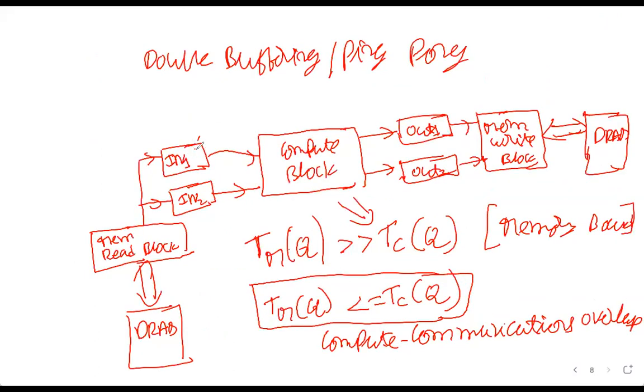The design of these buffers in1 and in2 is very important. The way it is drawn, it looks like a queue, but you want to have in1 divided into multiple partitions, and each partition allocated to a separate VRAM block. That way the compute block will get maximum bandwidth from this buffer. If these VRAM blocks have 2000 read ports, then the compute block will be able to do 2000 parallel reads and perform 2000 multiplications or additions.